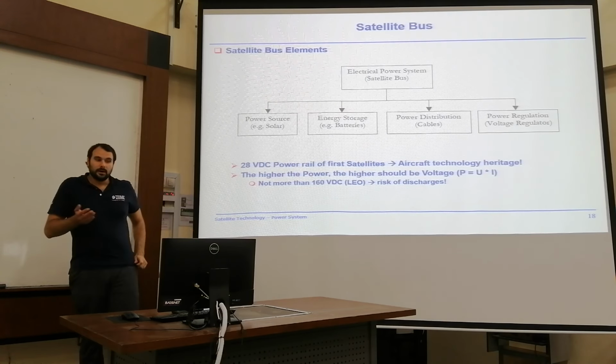And again, I have some real-life example here, again from the Flying Laptop satellite. This is a small block diagram of the power conditioning and distribution unit, PCDU, where you can see the solar panels connected here, 3 different panels for the 3 panels we have on board the satellite, and we have 3 battery strings on top there. So within the battery we have 3 separate battery strings, and every single battery string is connected to a corresponding solar panel. There's no interconnection there.